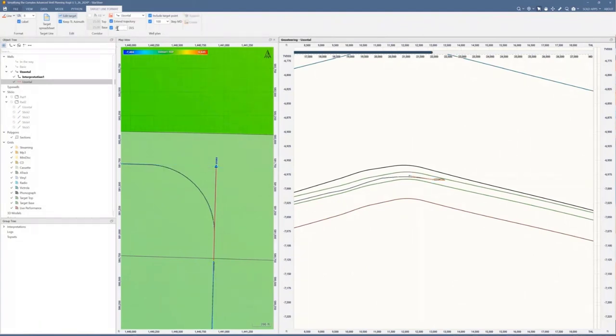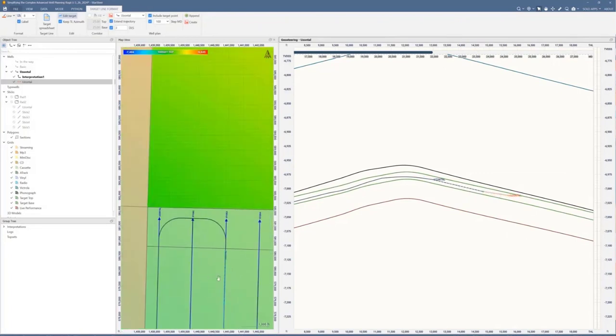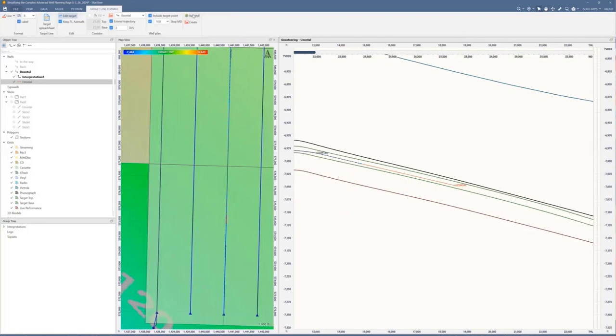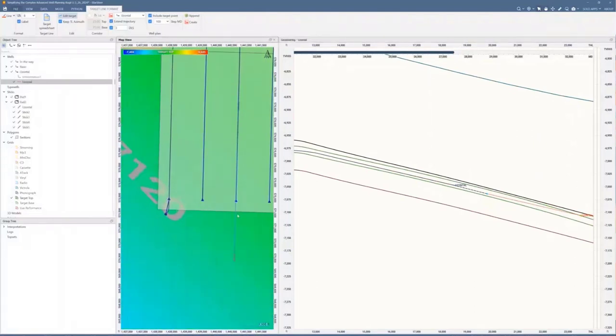And then this next one, I'm going to knock that back to 3 dogleg severity. And then I can just grab that target, bring it out. And luckily where this project is, this is the Bakken, so this is very easy structure. There's not many faults. I'm just going to hit append again. I'm going to bring that down as well. So what you're noticing is as I'm bringing this down, there's no limitation, right? So it's actually exceeding the landing point of stick 3, or where our TD is going to be.